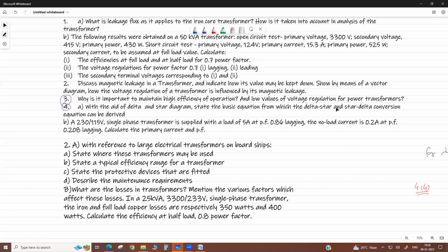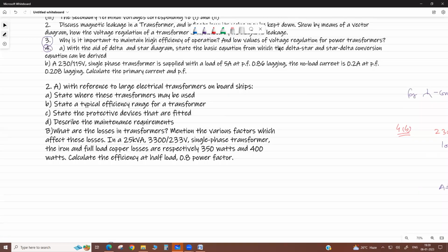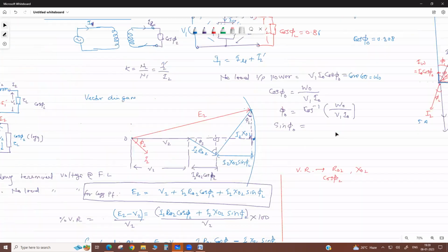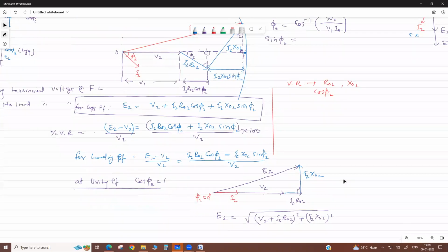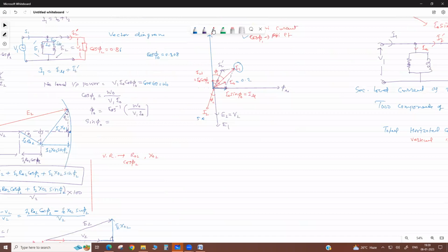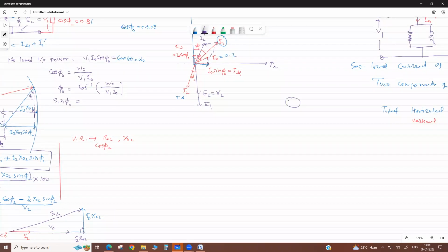Why is the value of voltage regulation kept low? High value of voltage regulation means the internal drop is high. Again, same thing. You know, the current increases if there is a voltage drop. And your motor terminals do not get the rated voltage. See, in a simple diagram, this is your transformer, suppose. This is your secondary. Due to this, there is a percentage impedance, which represents your equivalent impedance. This is your regulation. Then this is your main switchboard, MSB.